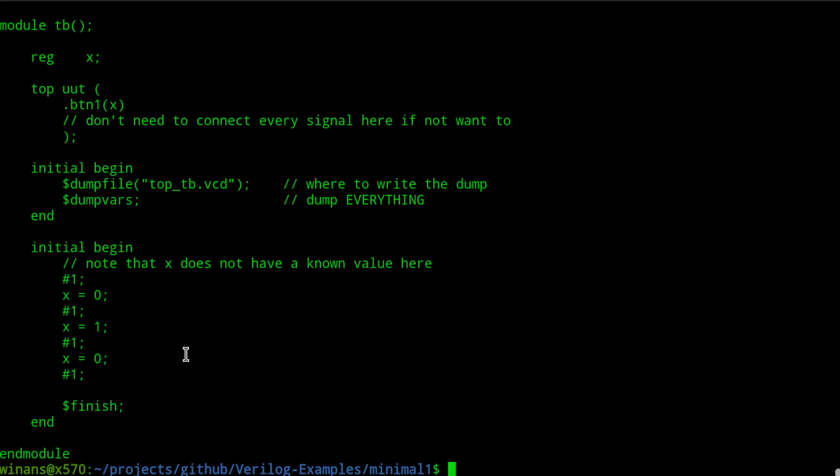The stuff that can exist inside of an FPGA is what I call the synthesizable subset of the language of Verilog or VHDL, right? The language can do a whole lot more than an FPGA can. And as I understand it, the language was invented not for programming FPGAs. It was invented to simulate an ASIC that somebody was designing. Later on, when FPGAs were invented, it became apparent that some aspects of this HDL, Verilog and VHDL, could be directly converted into a configuration file for the FPGA, which is kind of neat.